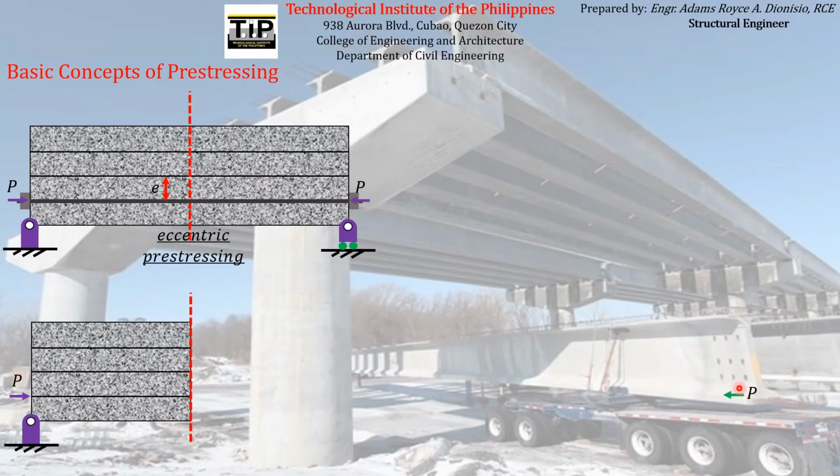So again, this internal force is acting on this location at a certain eccentricity E from the centroid. Now, if you can recall from statics of rigid bodies, we can move that force from this location to this location along the centroid of the cross-section. We can move that force according to statics of rigid body, given that we will also add the moment being produced by this original force to this line of action where we want it to be moved. So what is the moment being produced by this force to this location? So again, moment is equal to force times distance.